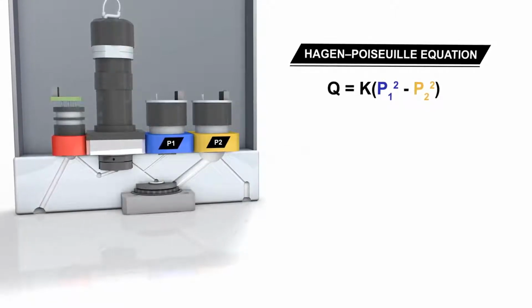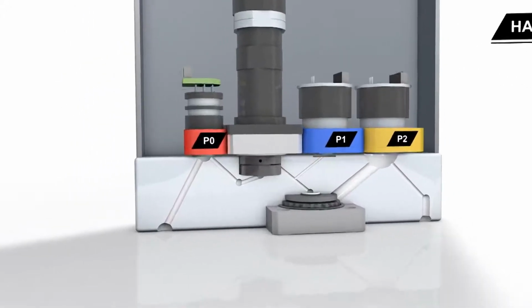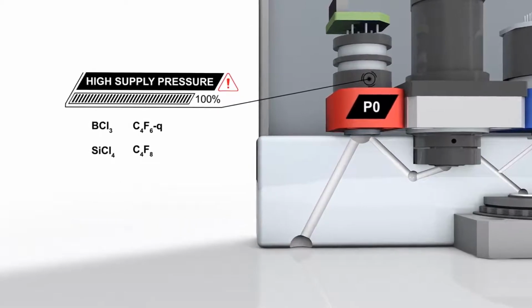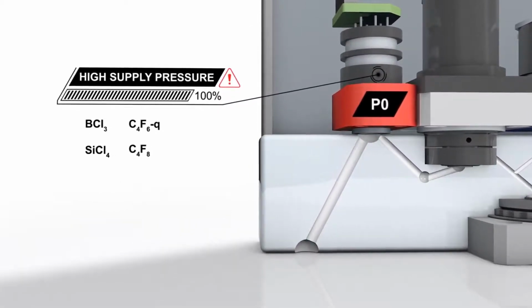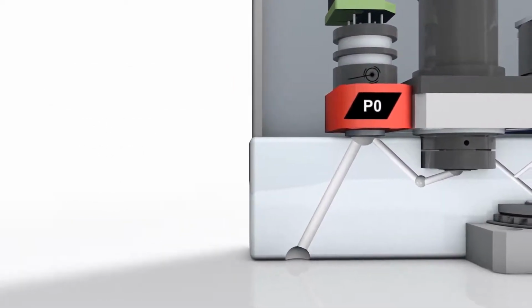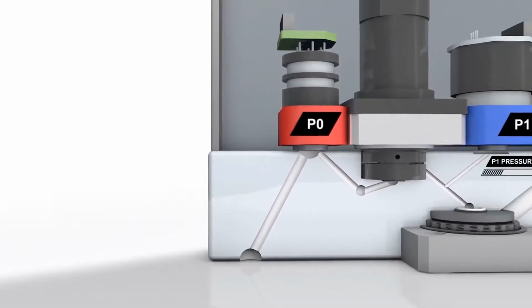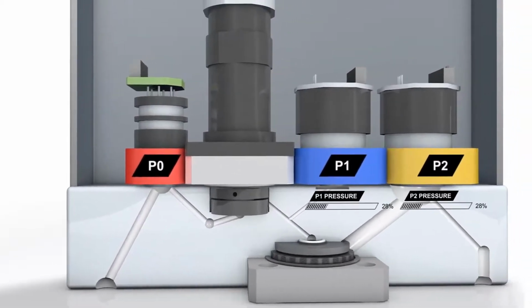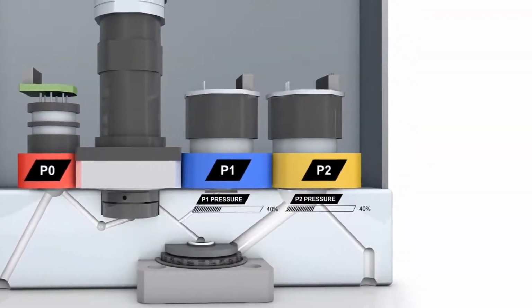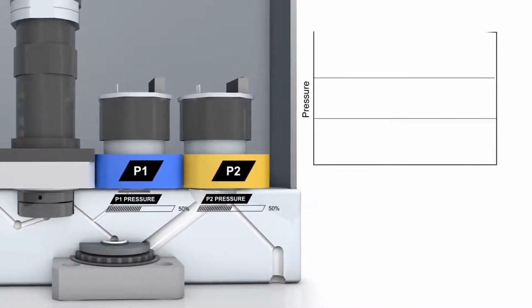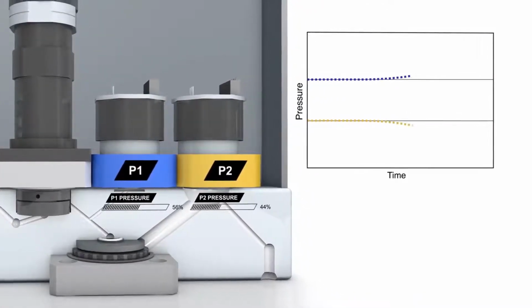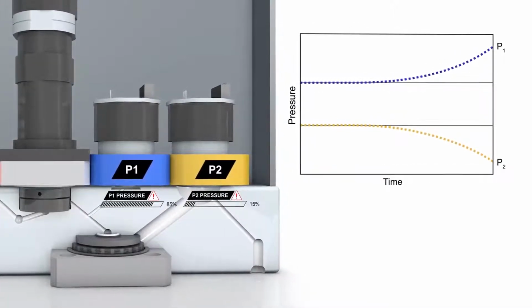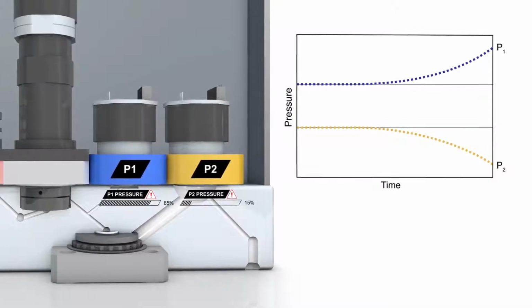However, the use of the upstream valve opens up many disadvantages. This design requires high pressure, making it suboptimal for critical low-pressure gases and low full-scale flow rate. This also means the two individual pressure transducers must be perfectly matched. By nature, all transducers exhibit some level of change over time. If they change by different amounts or in opposite directions, the product will become increasingly inaccurate as these offsets are squared in the mass flow rate calculation.